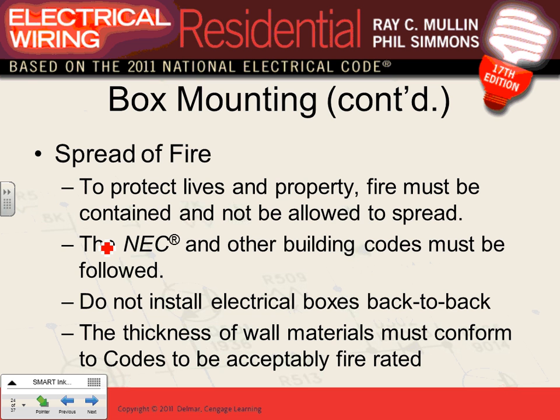Okay, everybody knows why we have the boxes: to protect lives and properties from the spread of fire. That's the whole idea of the boxes. Building codes also, we know what the NEC code says, put them in a box. Also, building code has to be followed, guys. Based on the building code, and that's also enforced, in a fire-rated wall, you can't put them back to back.